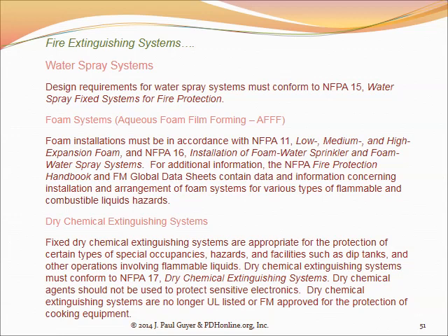The grease builds up in the exhaust duct, and that grease can catch fire. So what you often typically have is an automatic dry chemical system that senses a fire on the cooking surface or in the exhaust duct and discharges a dry chemical that smothers the fire. So dry chemical systems are something that you will run into commonly.